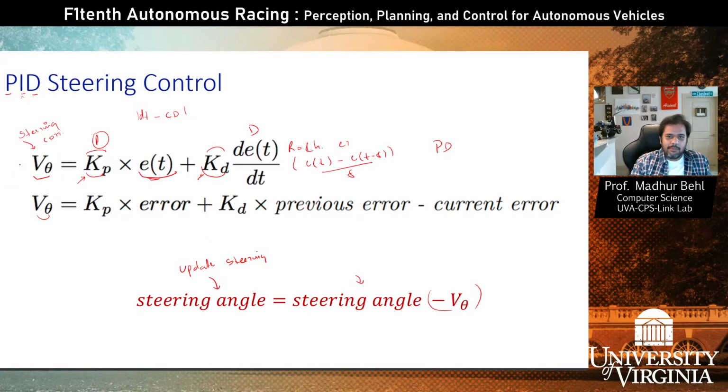And in combination of these two things, what will happen is your car moves, it always computes the value of this projected error based on this previous geometry, and it steers itself in response to the error, and in this case the derivative of the error, and continuously adjusts the steering value so that it can track the reference value, which is a certain distance away from the wall. Okay, so you have to implement this algorithm in the simulator, and then let me show you some more examples of the effects of these proportionality constants, and then we'll talk a little bit about the code as well.